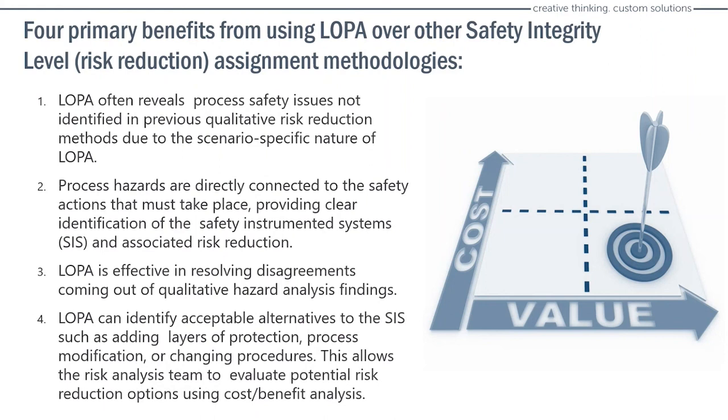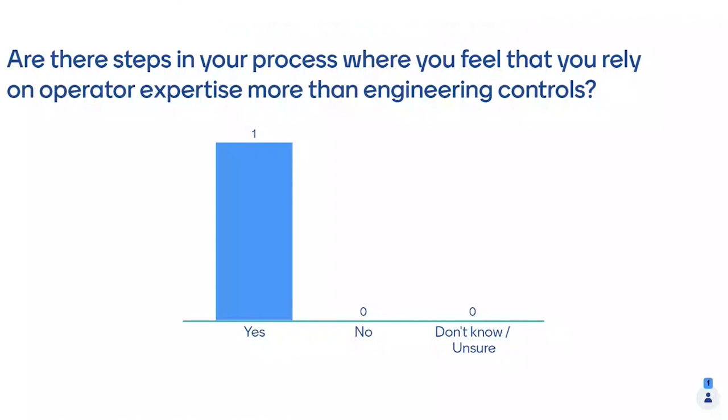This is not an obvious thing, and obviously there's going to be some disagreement over what is acceptable, and possibly a LOPA can help drive the discussion there over what is the benefit of, say, adding an integrated system or some sort of interlock to your system, and what's the cost of that versus the potential loss. So that's all something that you may want to think about.